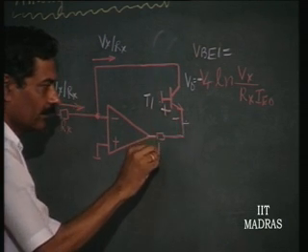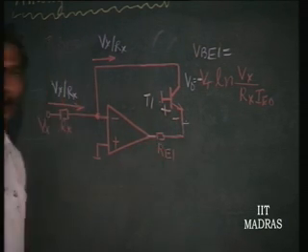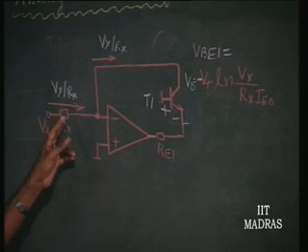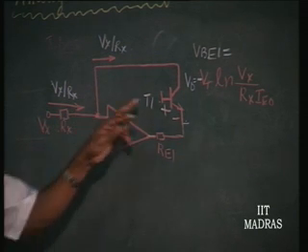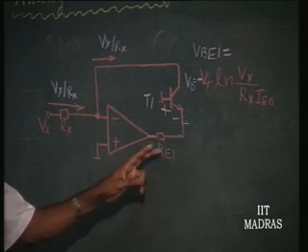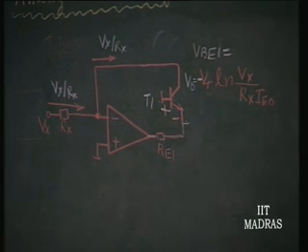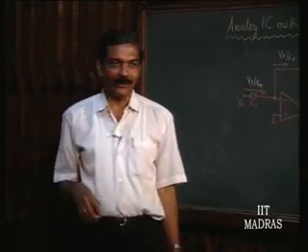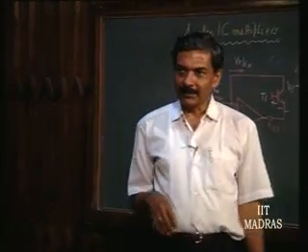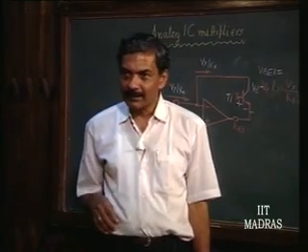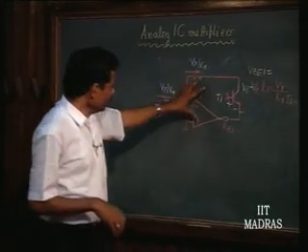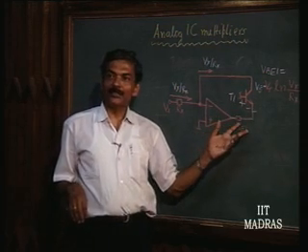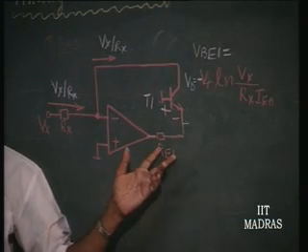so that the gain now is Rx by small r e plus Re1. So, you can reduce the gain to almost nearly 1, and therefore, resurrect this amplifier, which was going to oscillate otherwise because of its inherent frequency compensation being valid for its own maximum loop gain of A. So, this I can make it, you may think, as high as possible, but that is not so.